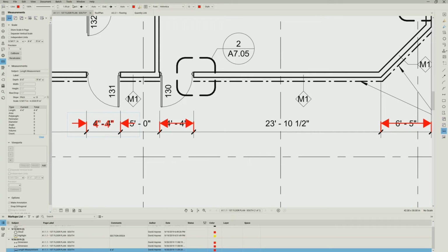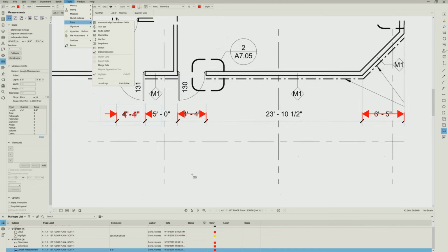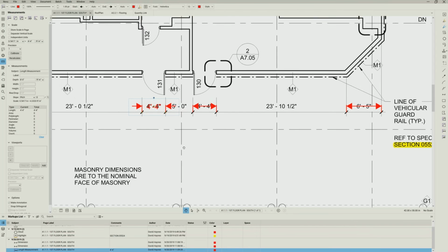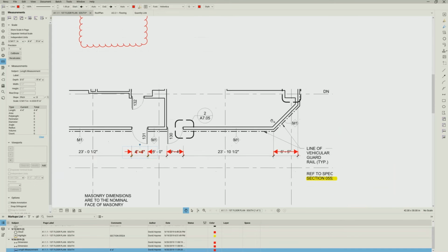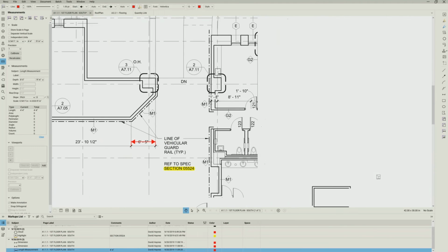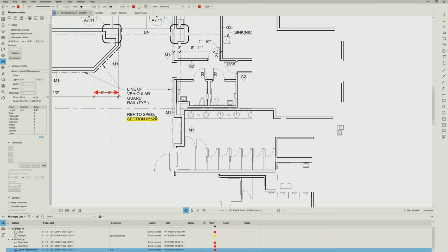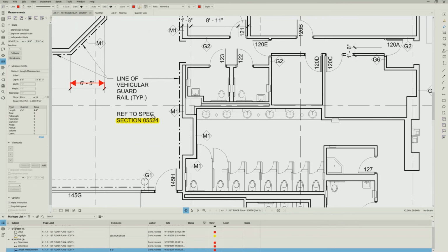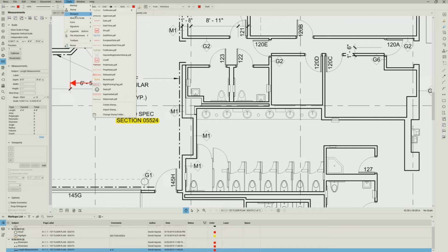All right, but most people use here the tools, measure, and here under the tools, measure, pull down, we get the different types. And I'm going to go through 3, though you could use any of them. The first one we're going to use is area. So let me find something that I want to find the area of. Now that I've done all of that good stuff, let's come over here. Give me just a second here to get this sort of centered and a little larger. All right. Tools, measure, area.